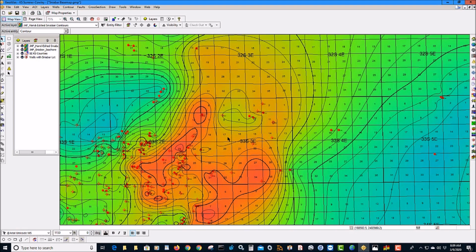Okay, and then you get your contour grid layer. It's got a grid. The grid is essentially conforming to your hand edits. And again, you can then do volumetrics or source a geomodeling surface to that grid, and then use that surface maybe to constrain other surfaces. So maybe it's a target surface for your horizontal wells. You want to make sure that the upper target surface is nailed by hand edits, and then you can constrain your lower target surface by that upper surface, and then your zone is really, really well defined based on your interpretation of the geology.